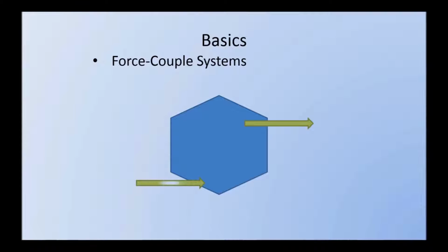Now we want to be able to compensate for this to balance everything correctly. So this is the location of the original force. As you can see, it's moved to the upper right. Now, we want to first balance the force, so we put an equal and opposite force in red, going the opposite direction of the green arrow. So that's done. But now, we also need to balance the moment.